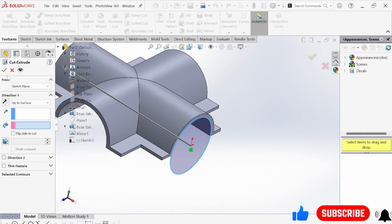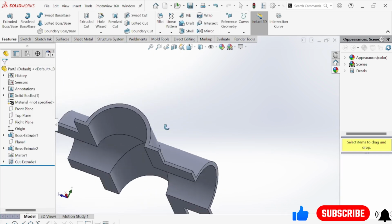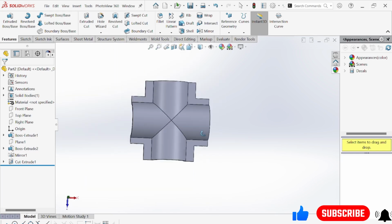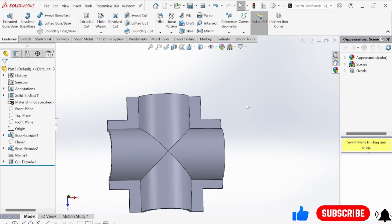This time we need to cut this thing completely. So select through all. Now here you see it will cut the entire surface. Now here you see it gets cut. This is our final part. Both the dimensions are equal. Let me check the dimension is equal or not.